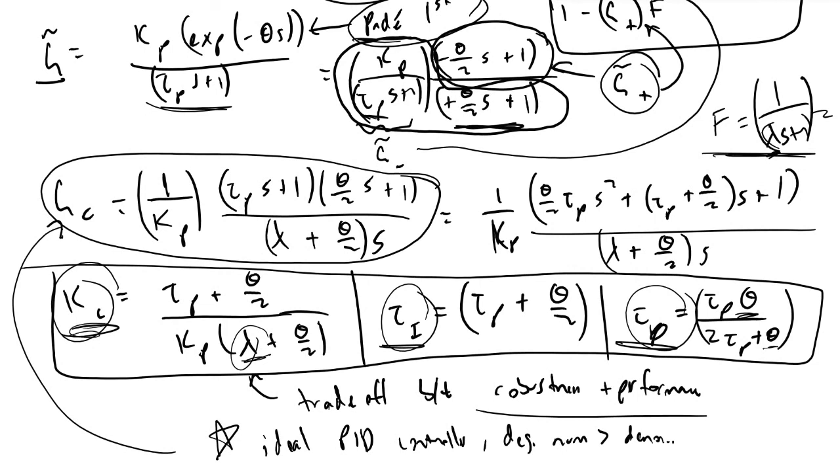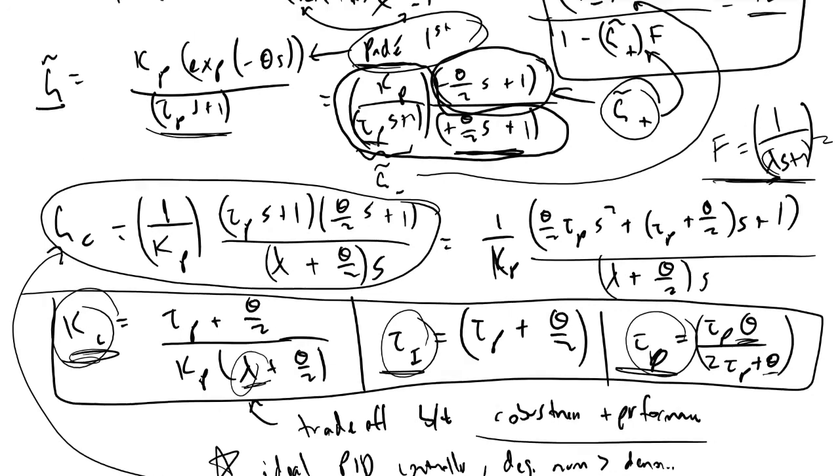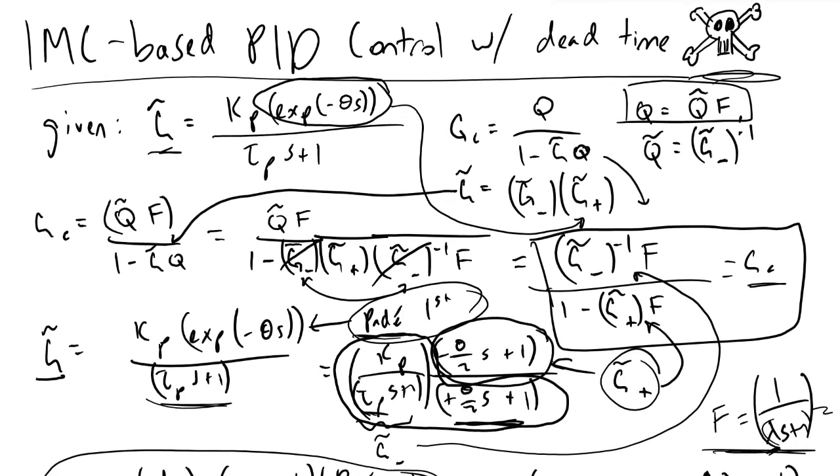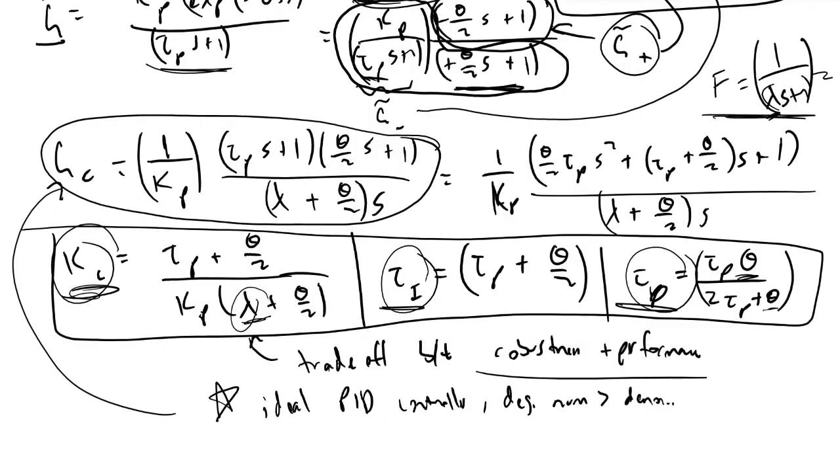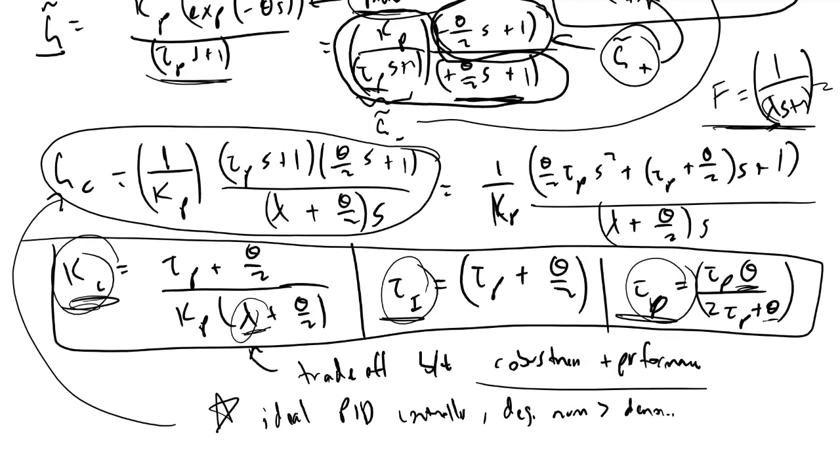So in practice what an engineer would do is you would be given some kind of process model, you would recognize that it's a first order process by looking at the degree of the denominator. You would see that it's a first order process. You would see that we've got a dead time present. We would go to a table, and people have already worked out that these are the appropriate tuning parameters to go with.